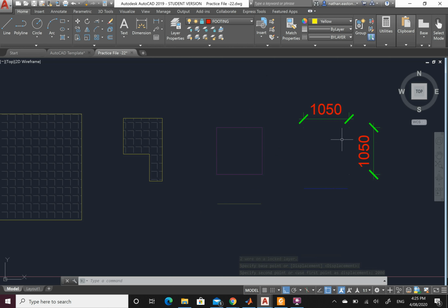Okay, this is going to come very useful when we start looking at larger plans. So it's very important that you put different things on different layers. To unlock, so I can use this again, just unlock it. So unlock and click the one you want to unlock, and that will unlock all lines or elements drawn under that layer. Alright, so really useful tool to go through.